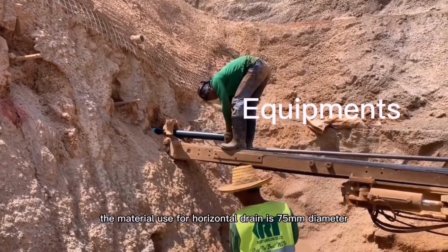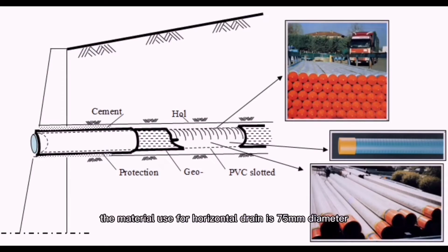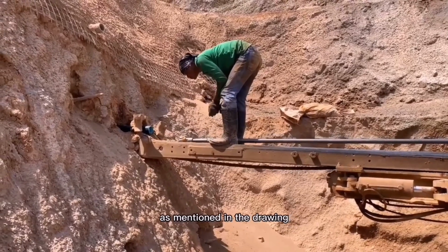As an example, the material used for the horizontal drain is 75mm diameter, minimum Class B PVC pipe with 75mm x 6mm slots at 200mm centers on the upper half of the horizontal pipe, and wrapped with non-woven geotextile. The horizontal drain should be spaced as mentioned in the drawing.